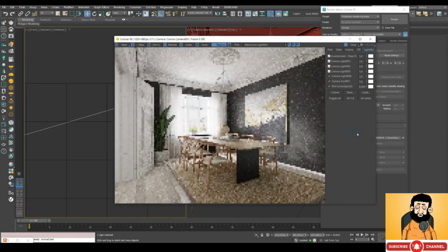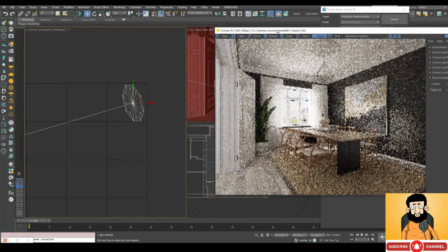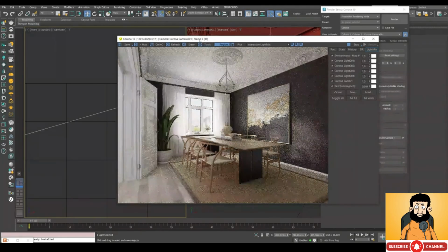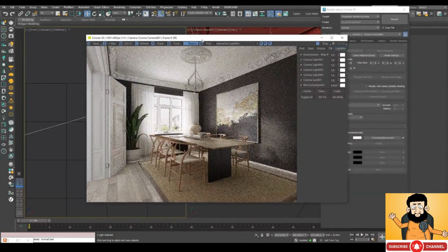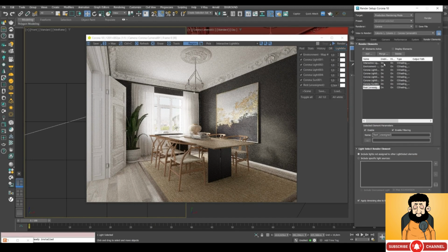The lightmix settings get assigned to the lights in our scene. Here in lightmix, everything except for the background goes back to default settings. And now we can delete lightmix layers in order to free up our RAM. Once again, lightmix uses plenty of memory. If you have a low performance computer with little RAM, you might start having problems with your final render. Your render will be crashing all the time, so it's better to get rid of lightmix layers once we're done